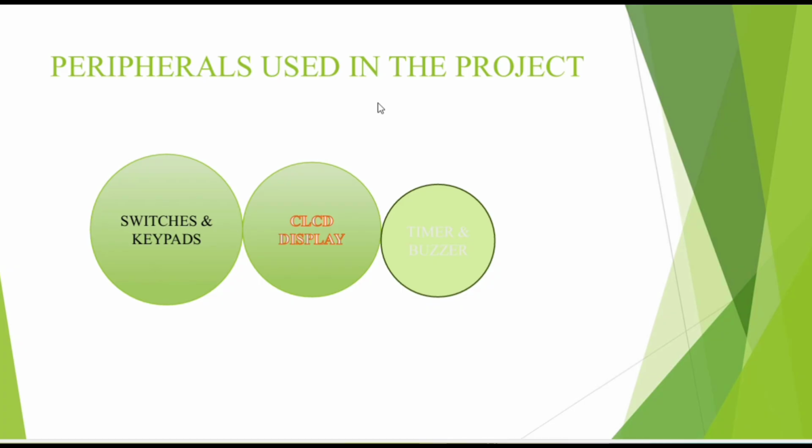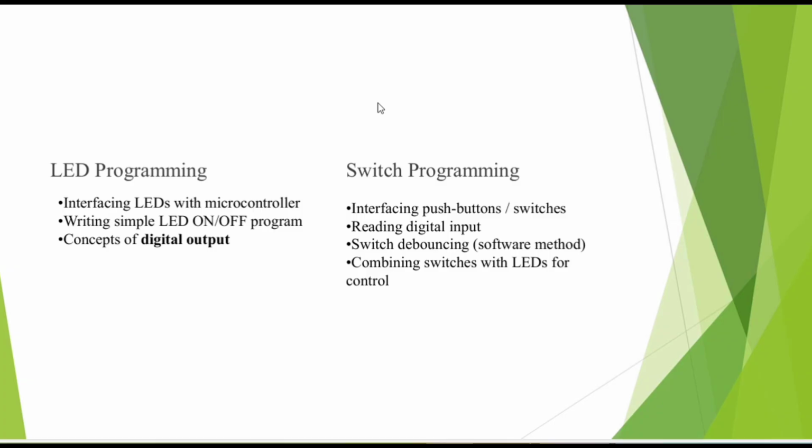In the next slide, we will see the LED programming and switch programming. In my internship, I learned the LED programming and switch programming. In the LED programming, that is interfacing LEDs with the microcontroller, writing a simple LED on program, which is the concept of digital output. Then switch programming is the interfacing of push buttons and switches, reading digital input, switch debouncing, which is a software method, and combining switches with LEDs for control.